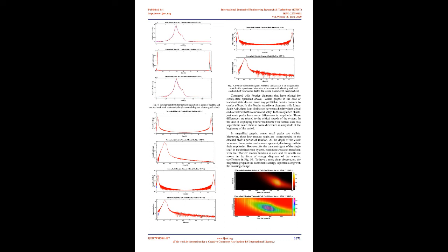Fig 6: energy diagram of continuous wavelet transform coefficients for rotor system with cracked shaft in steady-state operation and various crack depths. By a glance at the energy coefficients, it can be seen that the existence of a crack has caused some high energy points. Moreover, the intensity of these points is correlated with crack depth. Also, a separation due to the crack has been created at the top of the diagram.